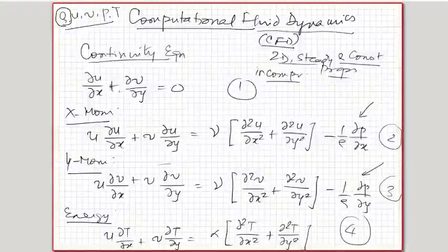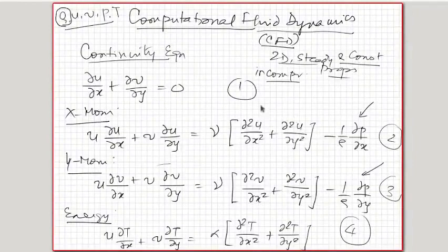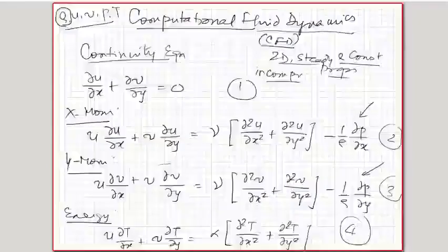This gives rise to an equation in pressure, and you solve that equation so that you get the pressure that satisfies the continuity equation, which can again be substituted back into the momentum equations. That kind of method is called the pressure correction method. So you get two different categories of methods in incompressible flows.